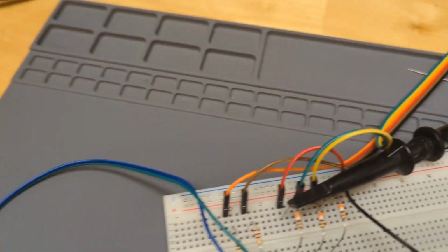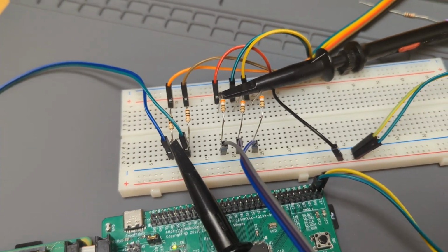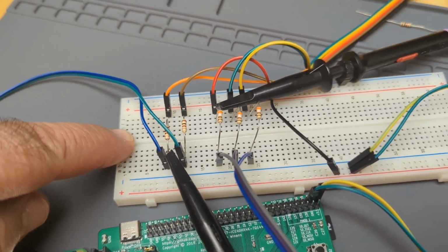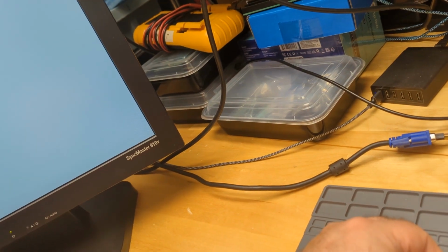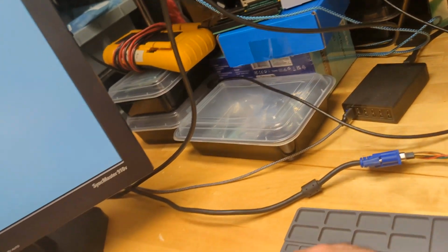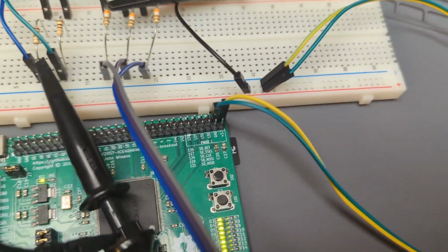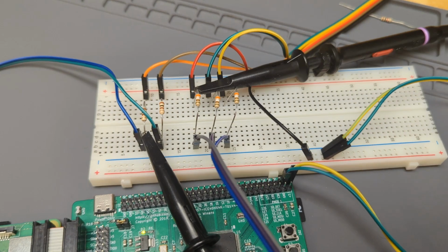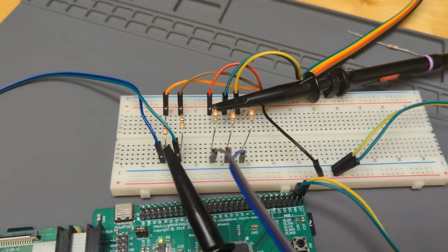These wires run around over here to, this is the crappiest breadboard I own. As I touch this thing, the screen glitches and flickers, and as you move these little things, I lose sync and everything. Oh, here we go. If I touch it again, the screen will go nuts. Of course, it doesn't do it now that I'm filming, but this is a really bad breadboard, so be careful if you use a crummy one. You might have to wiggle parts around a little bit. Here you go. Maybe you can see the screen going nuts if I just barely move one of those resistors.